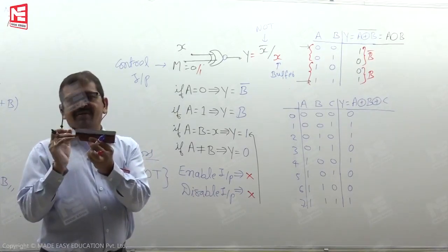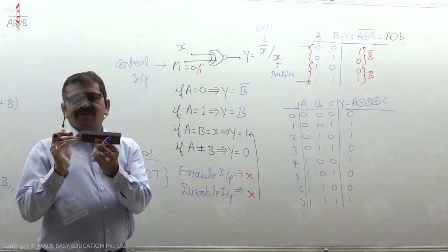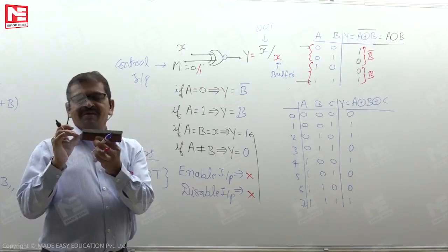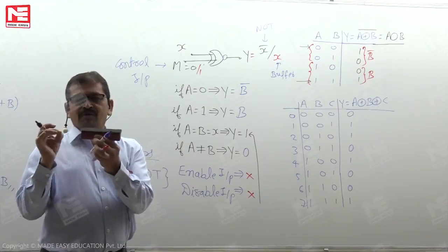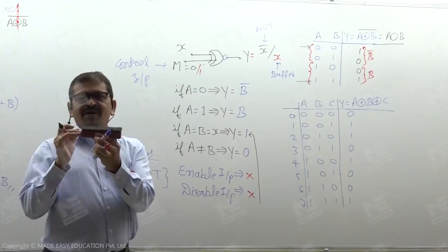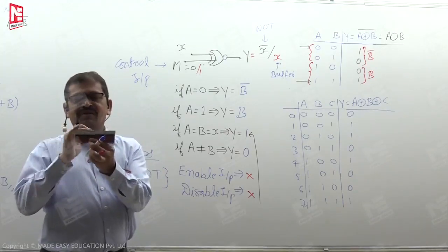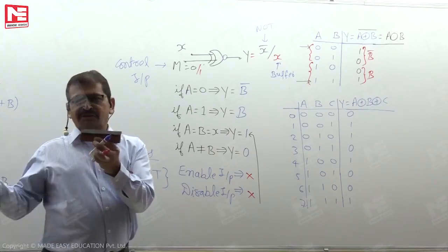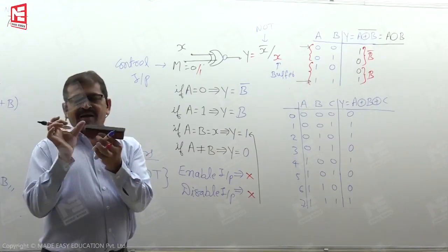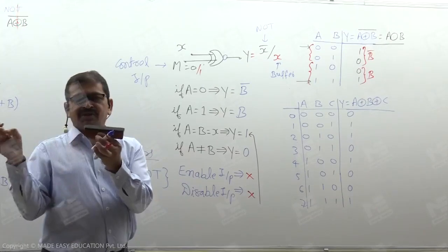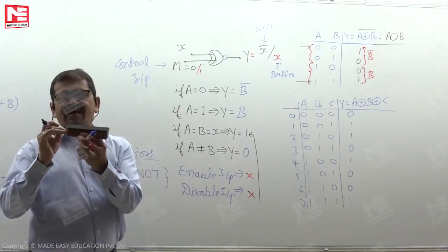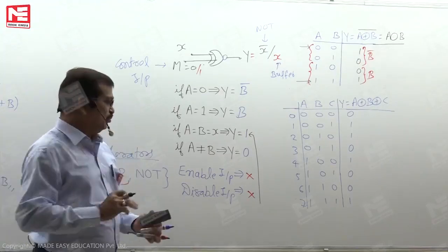If we have A and B as waveforms, whenever the A and B waveforms are coincident, 1 to 1, point to point, the same, then only do we get output 1. Whenever A and B are coincident for any duration of time, and for waveforms I am talking about point-wise same values, then only is the exclusive NOR gate output 1. Whenever they have coincident values, then only is the output 1.